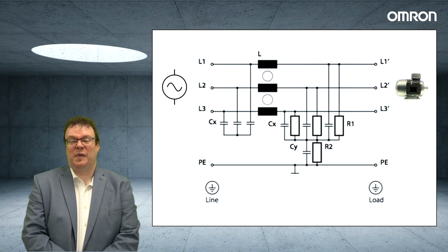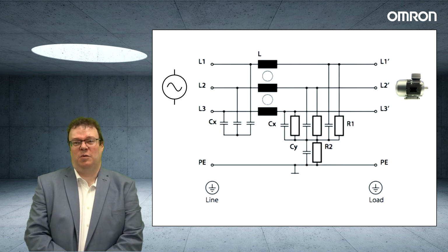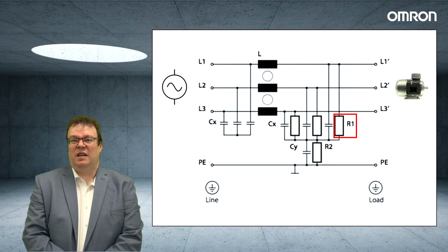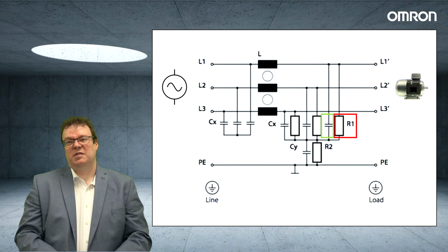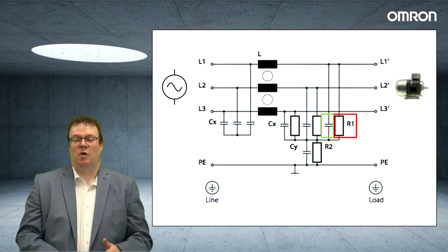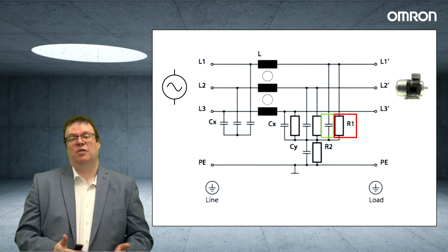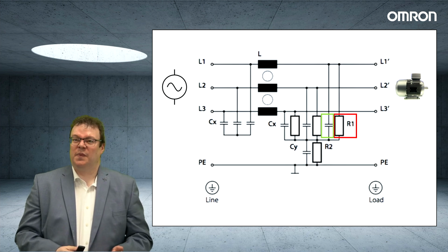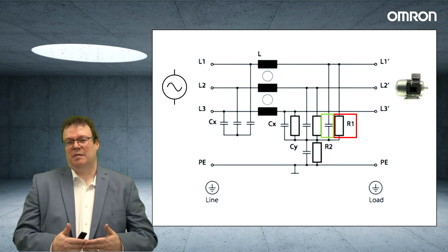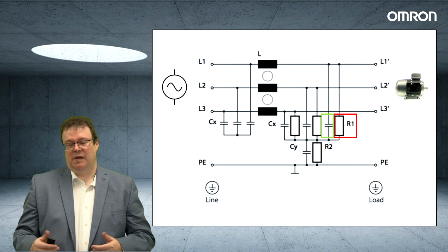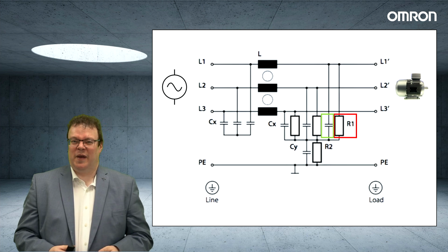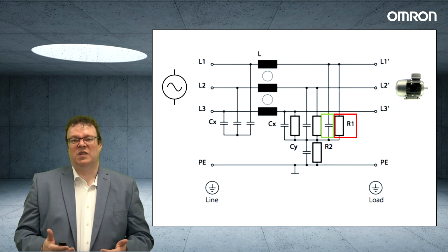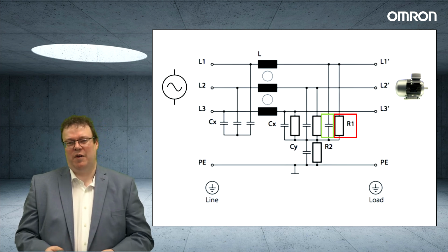How an EMC filter basically works is it utilizes a principle called a CR network. Inside there we have a resistor and a capacitor. In the case of high frequency noise or harmonic distortion, it can jump across a capacitor as if it was a dead short. So in the case of there being an EMC carrier noise running through the filter, the high frequency noise will jump across the capacitor to ground, and the low frequency, the power, will carry on to the motor.